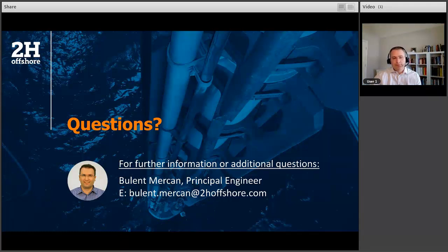Next question. Did you calculate riser fatigue using logger data in time domain? Yes, you can do that. The sensors are collecting data as time traces, so it's in time domain, and depending on the fatigue methodology, you can do fatigue calculations in time domain as well.